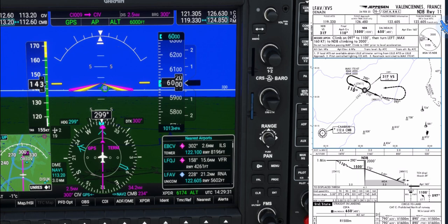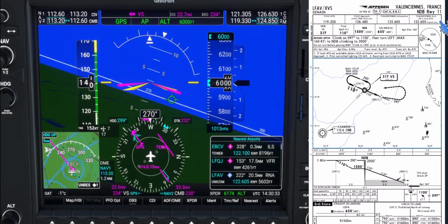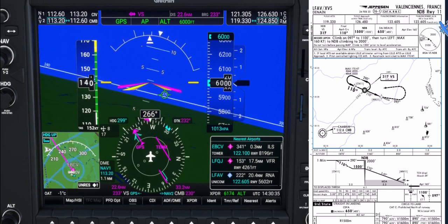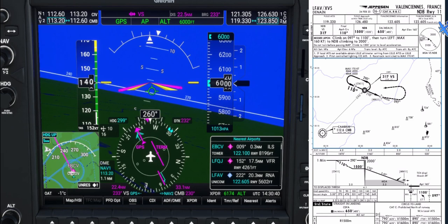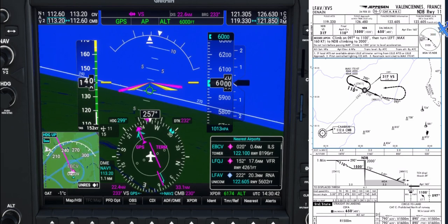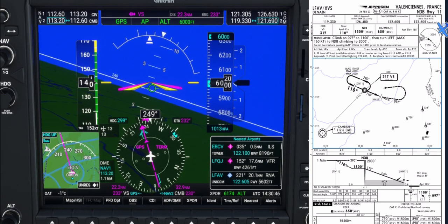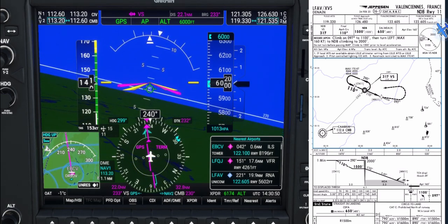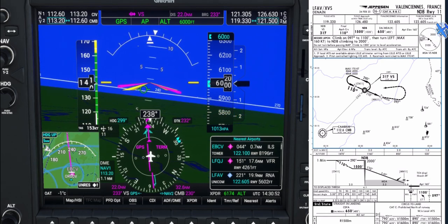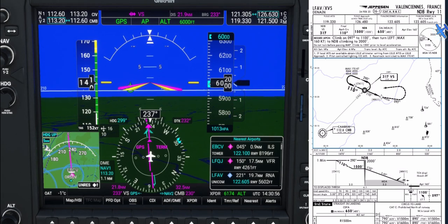Once finished with the cockpit preparation, which is asking for a complete review of the approach plate, you can brief the non-flying pilot or yourself if you are alone. Review the full approach plate in plan view and profile view with the different steps, check the minimas, check the go-around procedure, the MSA, what to do in case of downgrade, any restriction on the plate, check the airport plate for runway length, exit to taxiway, parking, talk about threats of the day and specials if any. All this is explained in the approach preparation module.